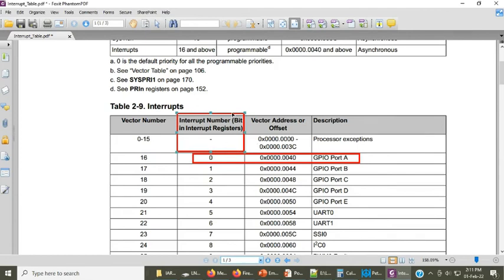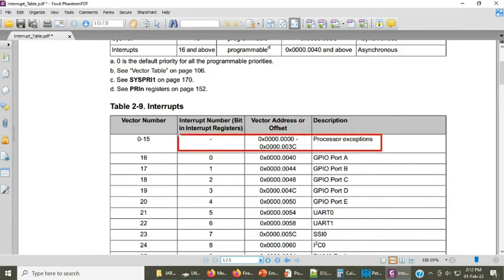Sometimes in many data sheets, if you study STM32 or some other microcontrollers, they may say that this interrupt is a negative interrupt, and you will think, what happened, why do we have negative interrupts? Those are not negative interrupts, rather those are exceptions, but the data sheet of that company preferred to write them as -1, -2, -3, and so onward. Please try to understand these things also.